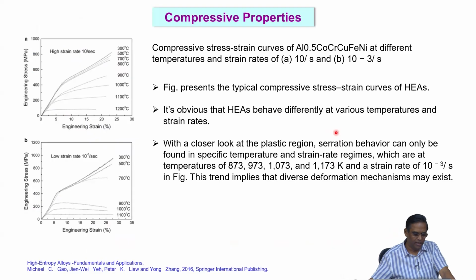Okay, so that is about the hardness. Then people wanted to study the strength. Usually we do strength measurements by the tensile test. That's a standard test. But in this particular case, people started doing only compressive tests because the volume of the material synthesized was too small to fabricate a tensile sample. A compression test can be done by just making a small cylinder, compressing it between 2 plate ends, and then measuring the strength and elongation.